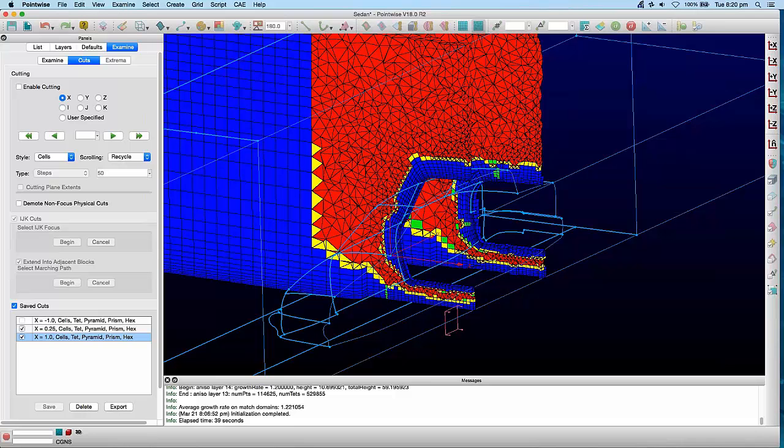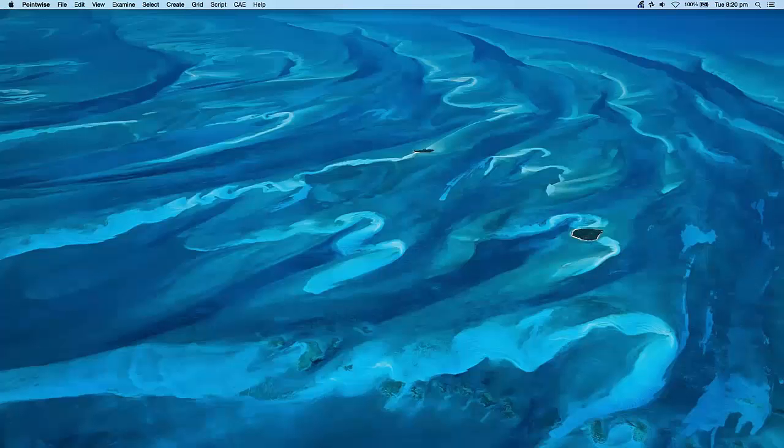So, why improve and develop aero through the season, even when you're confined by aero parity? There's a few things you can do there. One of the big things is getting an idea of the dynamic behaviour of the car. The car's not just sitting there 50 millimetres above the ground all the time. It'll be banking. You'll have effects from different modifications.